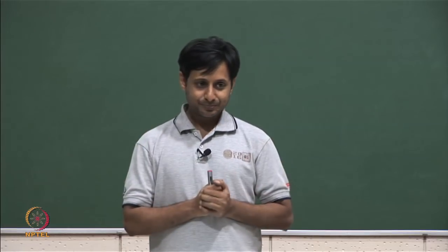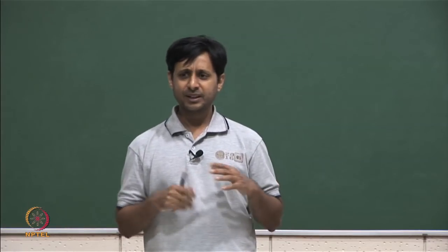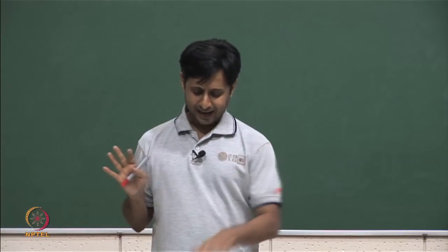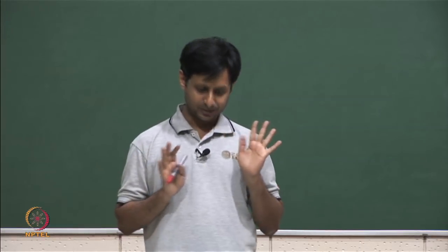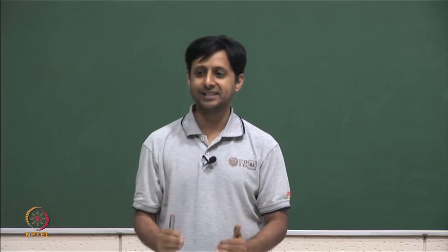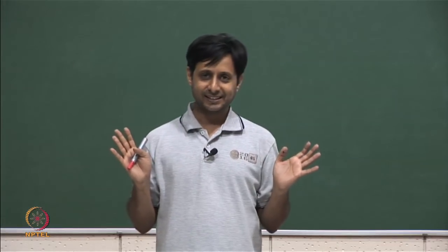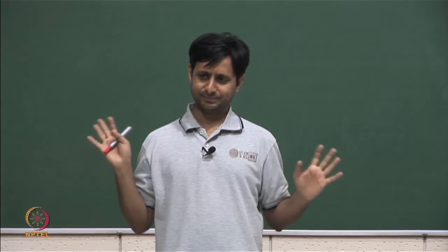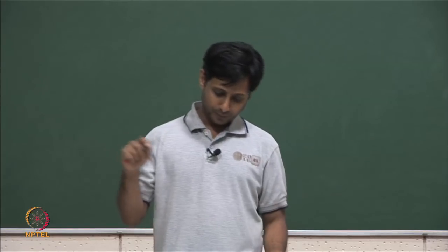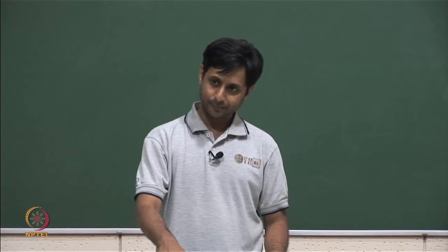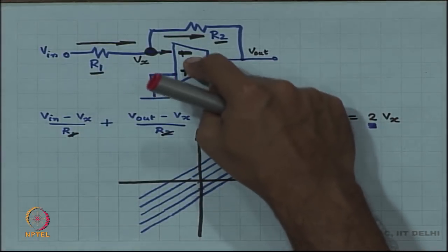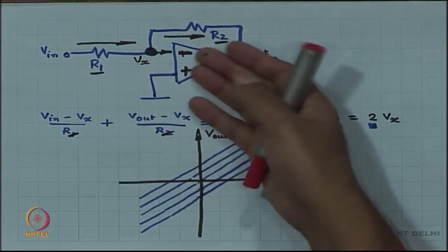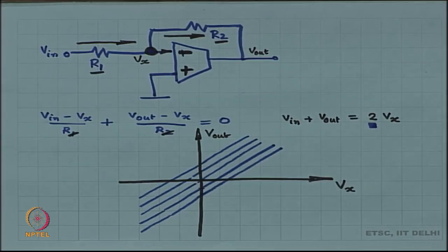So far so good. What have I done, by the way? I have not bothered with the device at all. I have only done one KCL, and this KCL is valid. Whether this device is an op amp or this device is an OTA or there is no device at all, it does not matter. Even if there is no device, it is okay, the KCL is still valid.